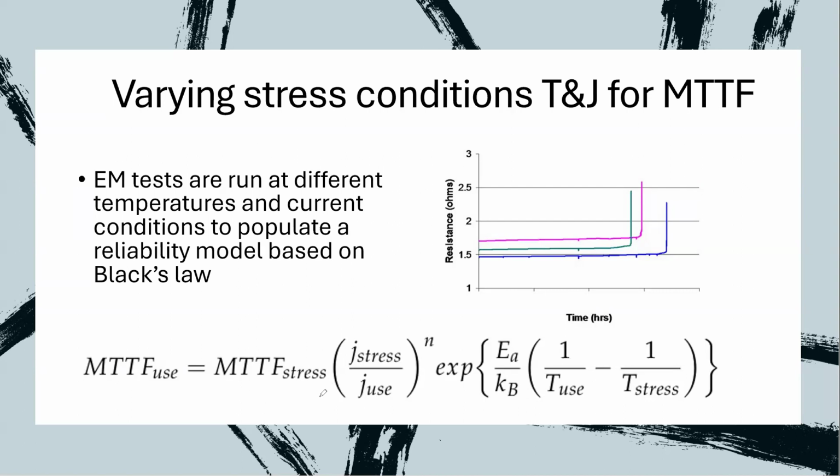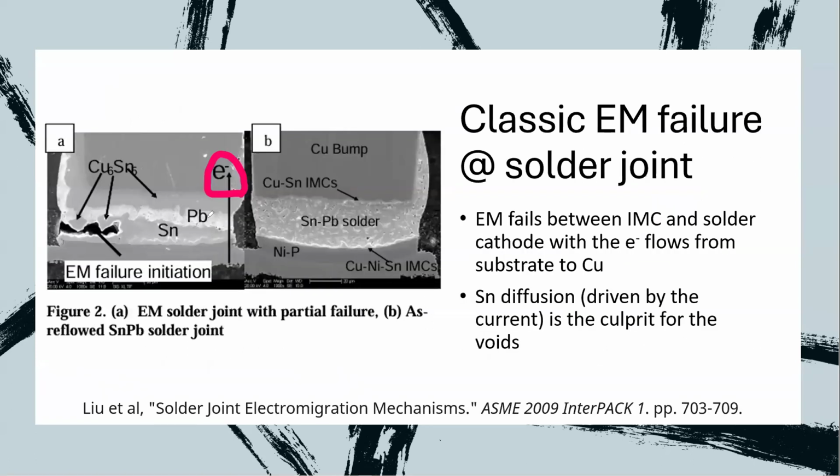Then we have to stress the device in a way. Say, I'm doing only 1,000 hours, and that's equivalent to 5 years. Okay, well, how do you convince me to do that? Well, Black's equation shows that I could do that by changing temperature and the stress or current. Okay, if you agree with Black's equation hypothesis, then you're fine, right? And let's look at the failures.